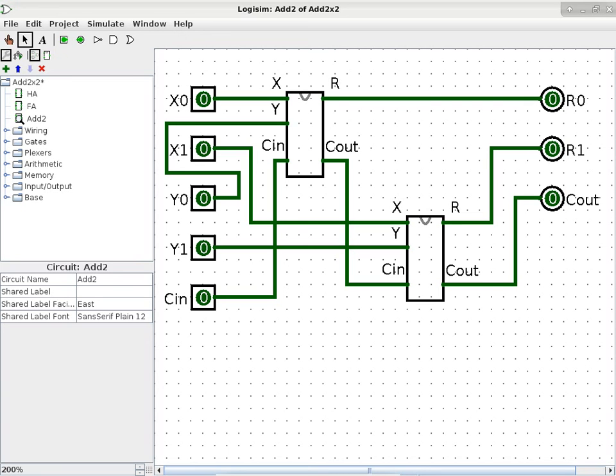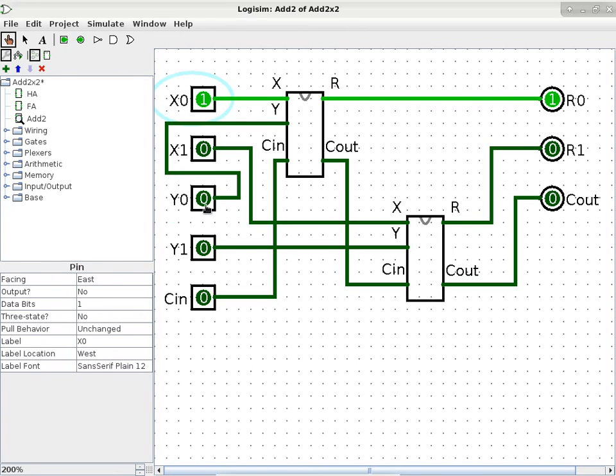All right, so now we have a 2-bit adder, and with a 2-bit adder, there are a lot of test cases. So I'm not going to test every single case. I'll just test some really obvious ones, like 1, 1 plus 0, 1 is going to be 1, 0, 0, okay? So we have 1, 1 as the first number, and then 0, 1 as the second number. I should end up with 1, 0, 0, which is the carry being 1, and then both results being 0, okay? So do your own tests. Find out what cases are the most representative, and then test it.